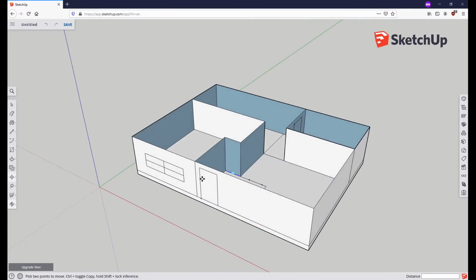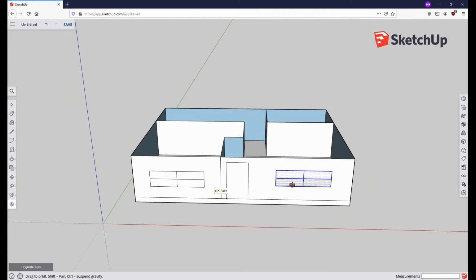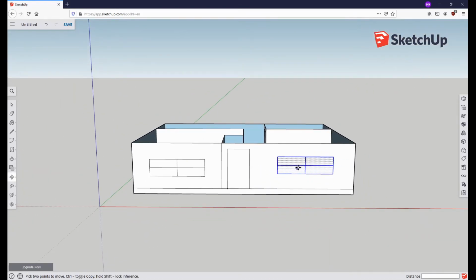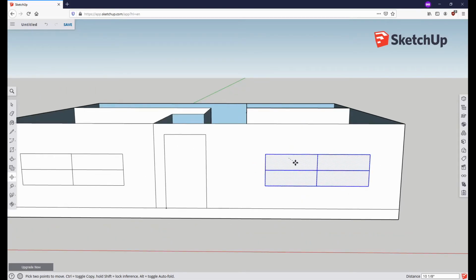And you know what, let's go ahead and add some extra light to our place. So selecting it, hitting Control C and then Control V on the keyboard, or Command C and V for those on Mac, you can simply copy that over. And since it's just that one flat geometric shape selected, you can simply move it without affecting the rest of the geometry on the wall. And we can simply put it into place.